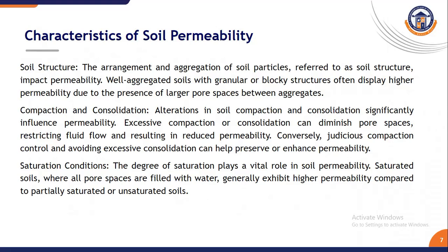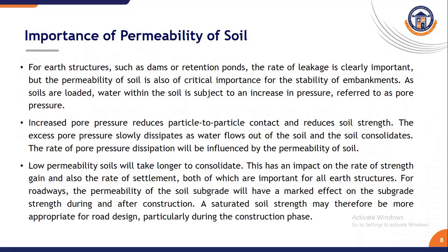Fully saturated soils allow a continuous flow path, resulting in higher permeability. According to the Lambe and Whitman theorem, permeability decreases exponentially with reduction in void ratio, especially in fine grained soil. Okay.